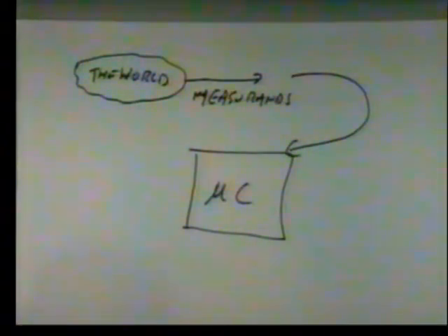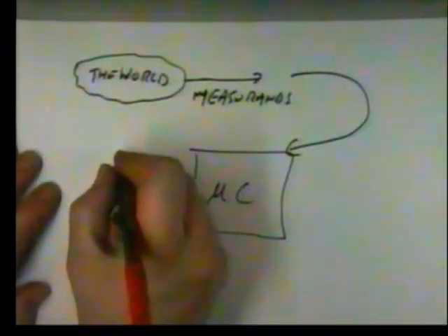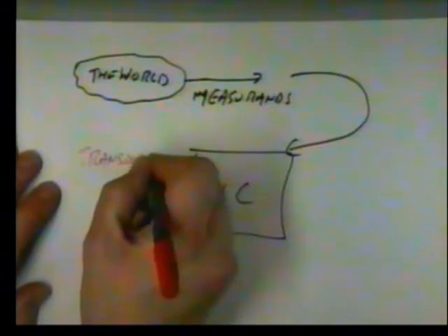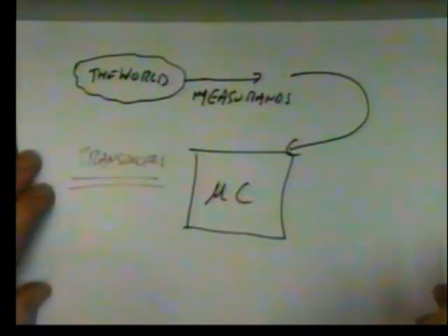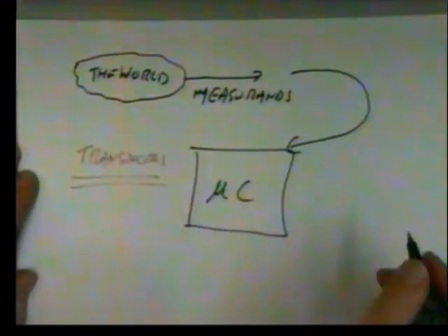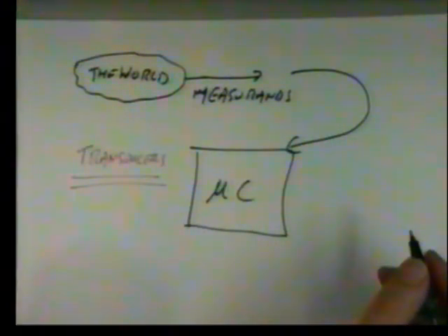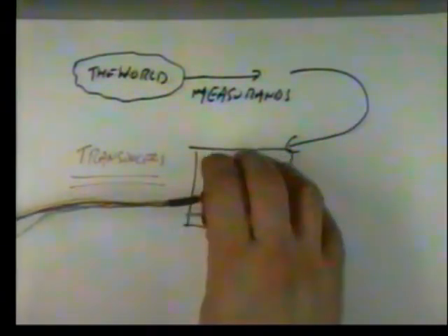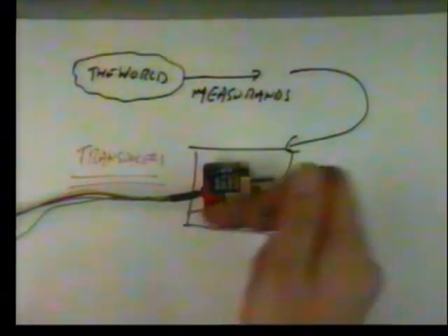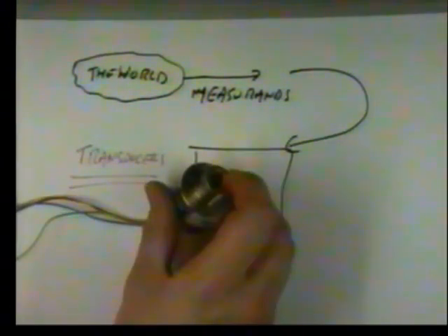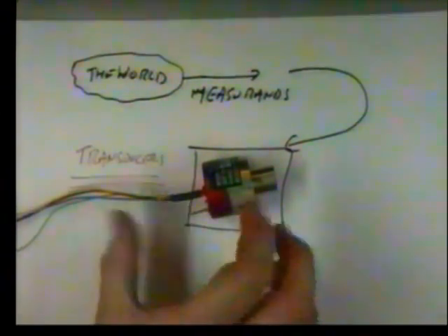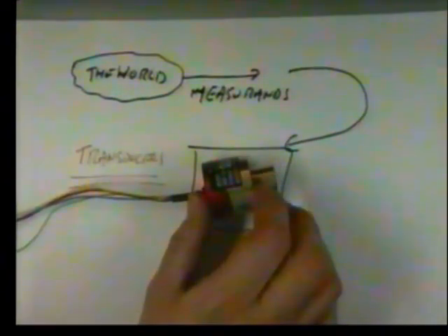How? Well, we've looked at the various tools to do that. Starting point is transducers. Most important, transducers. These are components that will convert one form of measurand into another form of measurand. For example, as we'll look at later, here we have the pressure cell where air forces into the pipe, distorts the metal, and we get a capacitive effect that then gives us an electrical signal we can monitor.